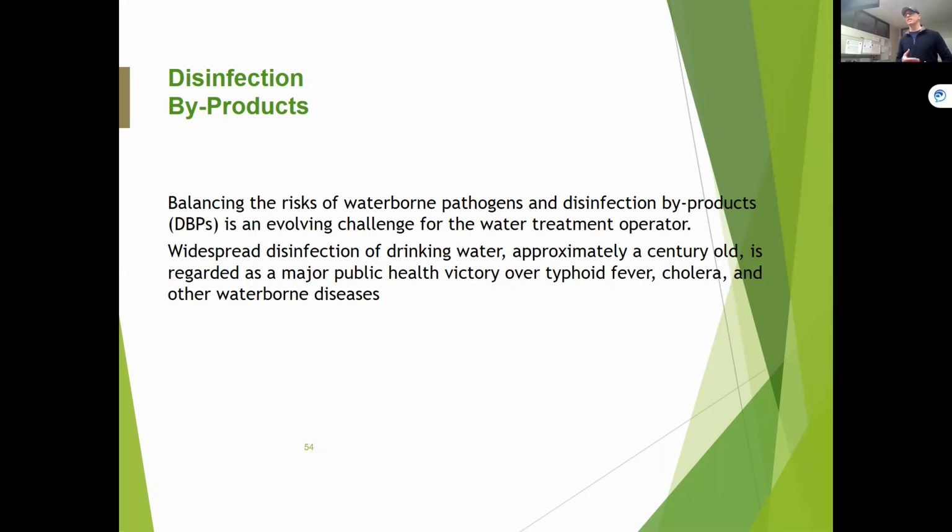So I'd rather take the guarantee that if I put chlorine in my water, I'm going to be safe. You have to weigh those two things. By treating the water, knowing more about getting organics out of the water, and protecting your watershed, getting the organics out through treatment processes before you put chlorine in the water is super important. I can't stress that enough.